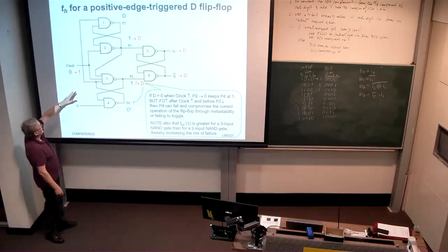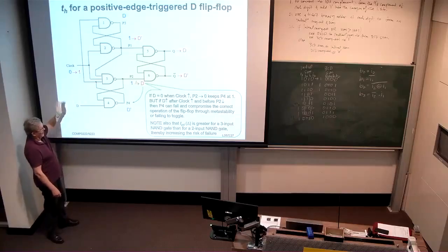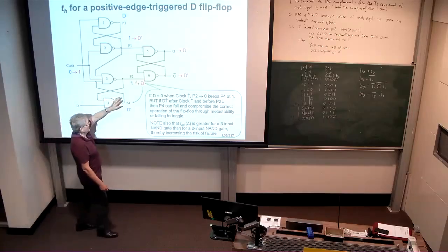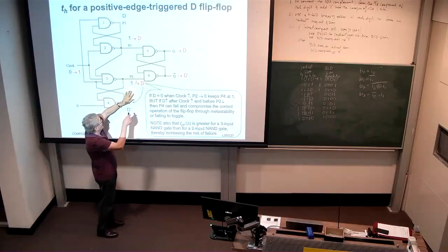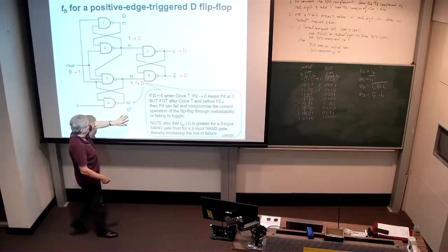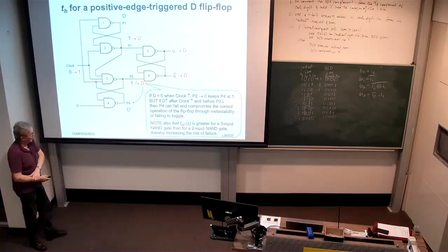Here we make the assumption with our positive edge triggered D-type flip-flop that the clock goes to 1 at some instant in time, and we know that that means we're going to get changes in P1 and P2 in response to what the data input is.